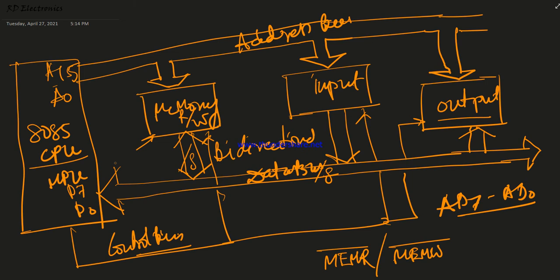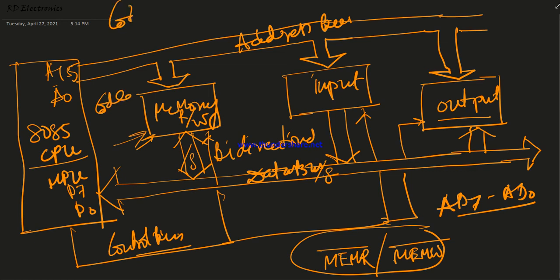Either from the 8085 the data goes from the accumulator to memory or from memory to accumulator, vice versa. So that's why we have memory read bar and memory write bar. One important point: the 8085 uses von Neumann architecture, so in the same memory we write both code and data. The concept is that both code and data are written in this read-write memory. So that's why this is bidirectional.